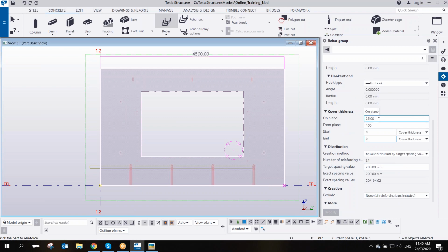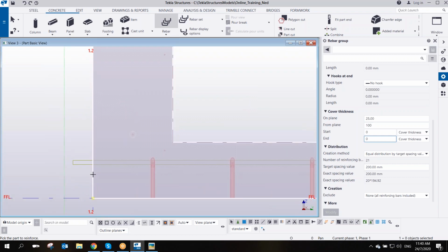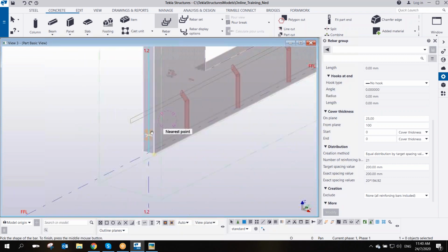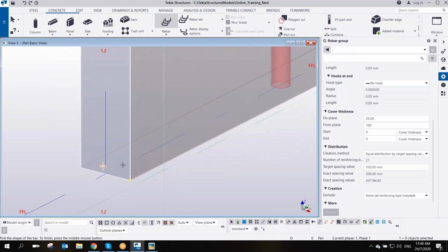All right. So select the wall. And then from here, press the control key. Because I don't have the reference, I'm going to press the control key, select, and then let's say here 500. Okay, click without pressing the control key, and then here, let's say 600.